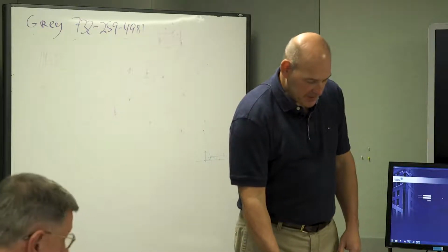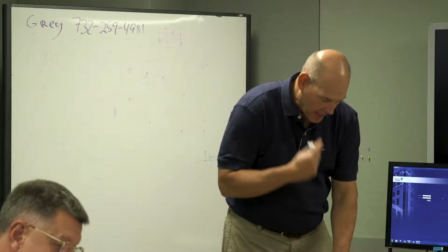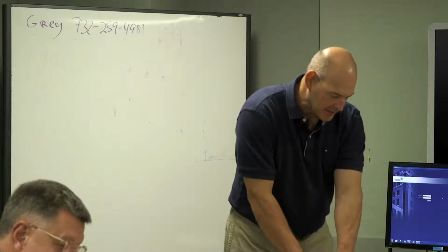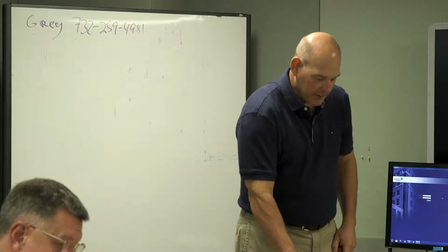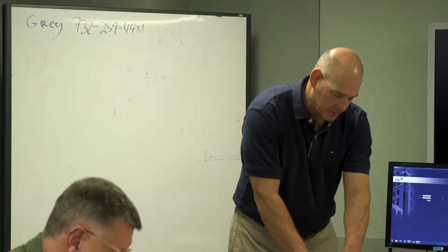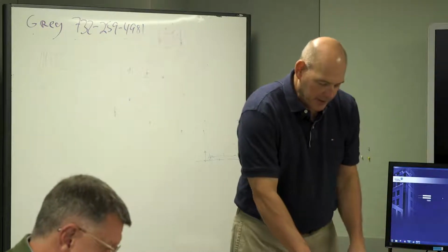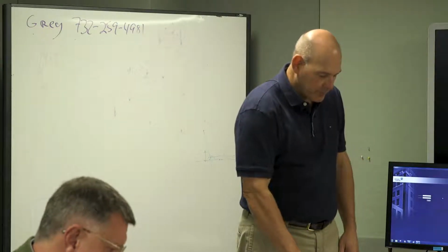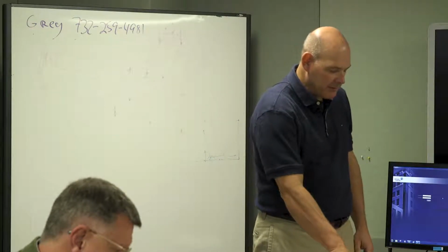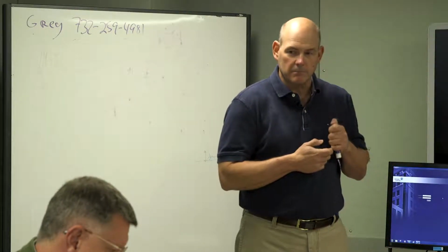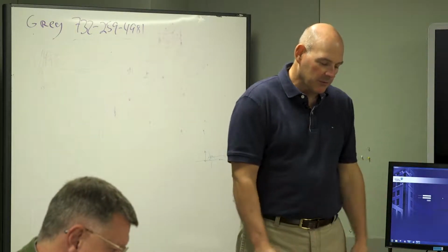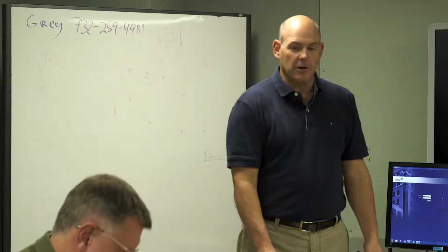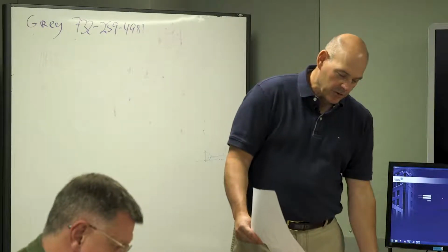So that's the purpose of the IOMs. And again, everything that's mounted inside the panel, relays and everything, is in the bill of materials. So your IOMs are in there, your power supplies, your transformers, everything you need to rebuild the panel should be listed on the top right-hand corner. And again, there are UPSs in these panels, and we'll have a demonstration of how the UPS works. They have a battery in them, basically, to make sure that when your generator comes on, you're good.